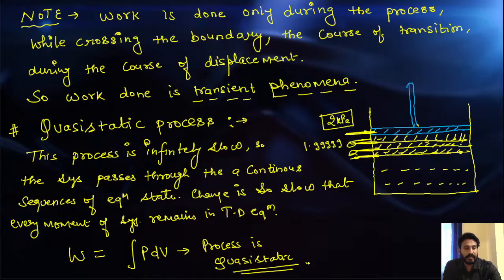So if you see the word quasi-static, don't get confused about what this quasi-static is. If the question says that the process is quasi-static, and at any condition this is my pressure, this is the value of the volume, calculate the work done, you can apply the integration of PdV, that's it, nothing else. You can calculate this directly, there is no problem with that.